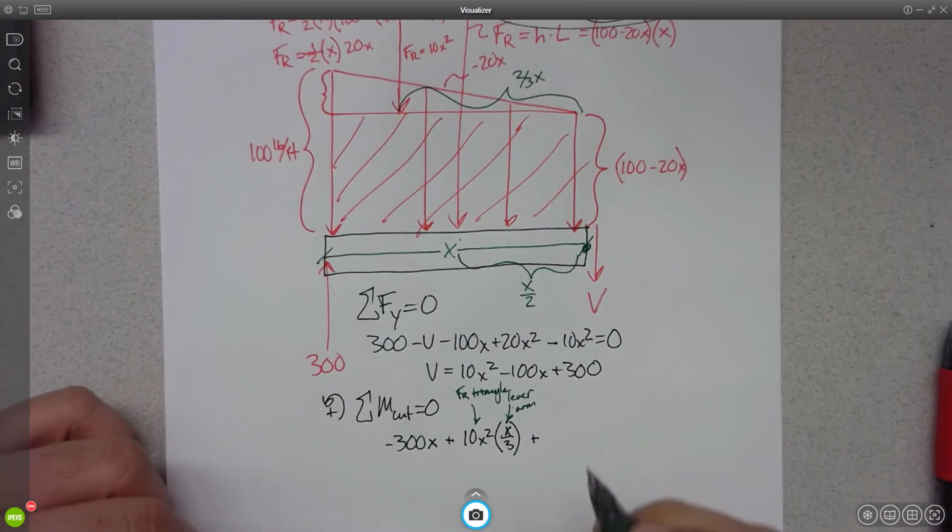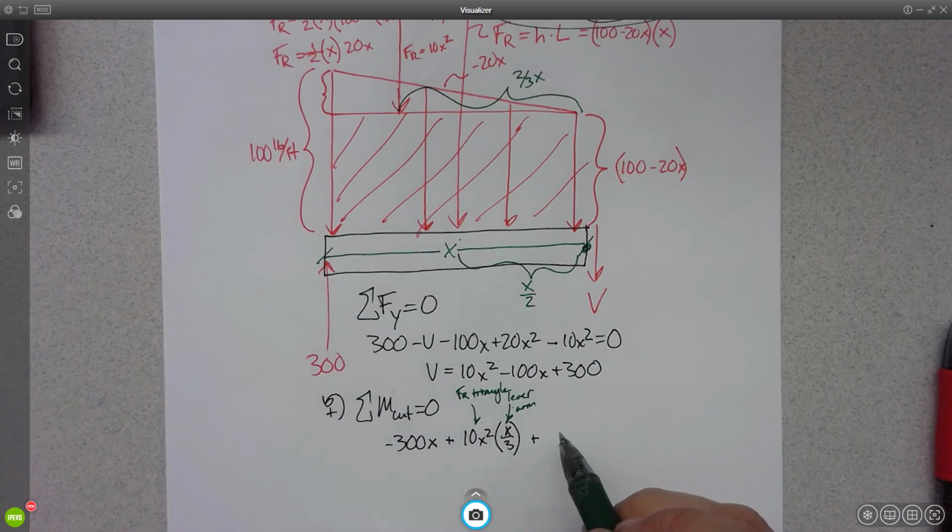My head hurts. Why don't I just take the integral of the shear? That would just tell me the change. It wouldn't tell me where it is. But that would give you the equation of the moment. You take the shear equation and you take the integral, that'll give you the equation of the moment. That only gives you the change, right?